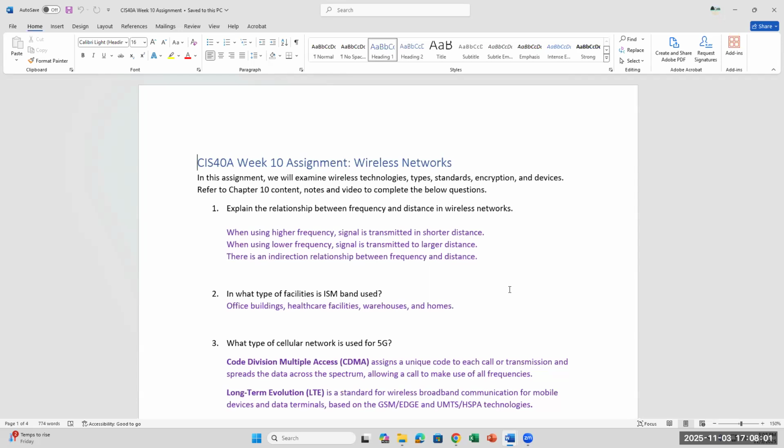And this is why, as I mentioned, you see a lot of smart technology like wearable devices, or even at the hospital to monitor patients' hearts, operating at 2.4 gigahertz instead of 5G. Now, current technology is equipped with dual band. Just keep in mind that when you go with higher frequency, you have shorter distance, right?